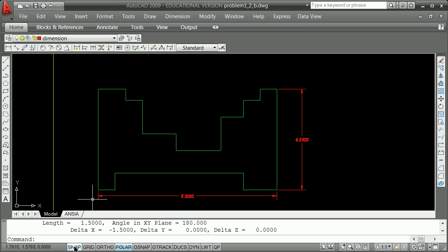1-3 I will do all with offsets and then relative coordinates by typing. And these skills, playing around with them and flipping them in and out, will help, especially if you establish very strongly how much you can do by scripting. And you don't necessarily have to run a script file to do scripting. We'll call it, if I say line and then at distance less than and then in an angle, that is scripting as well. You do not have to do scripting in a script file.